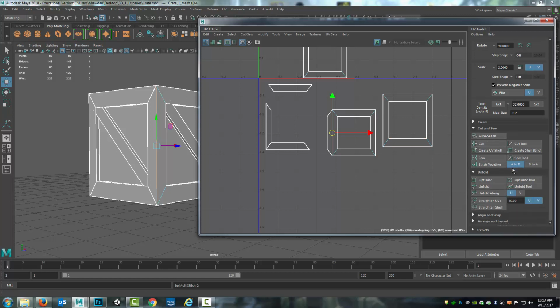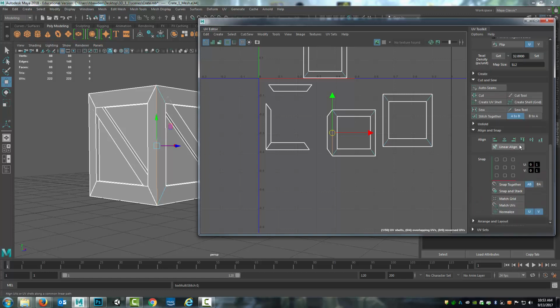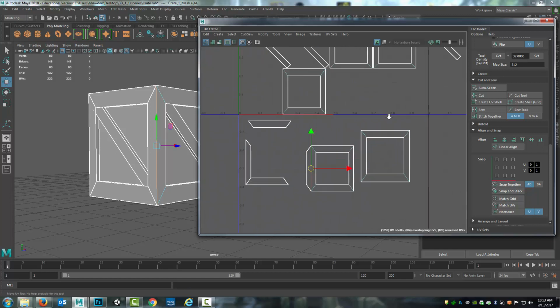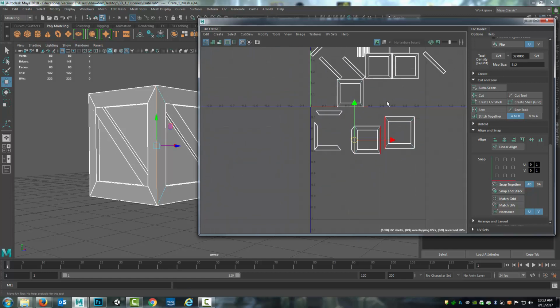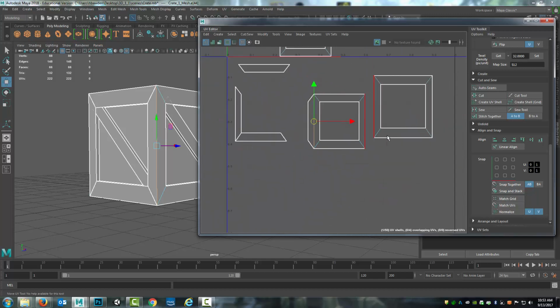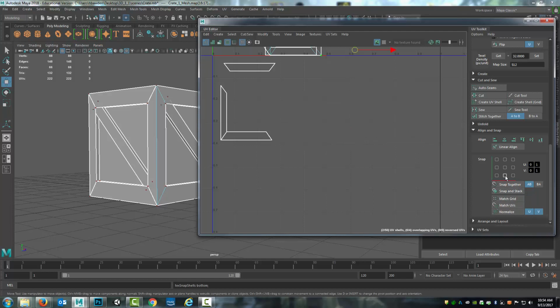There are many other tools that have helped to simplify and make things a little bit better. The other ones I want to point out for right now, though, for this module, are the snap tools. So there are certain cases where things may not line up the way you want them to. For example, if I want these UVs to be lined up with this shape, I can snap.